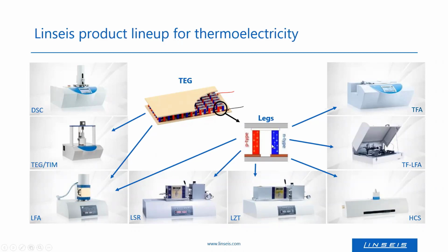So for the legs, one can, for example, use the LFA in combination with DSC for determining the thermal conductivity, the LSR, the LZD, the HCS, and for thin films, the TFA and TFLFA. For the thermoelectric generators, one can use the TEG tester or also the LFA, for example, for determining the properties of the ceramic plates on top and on the bottom.